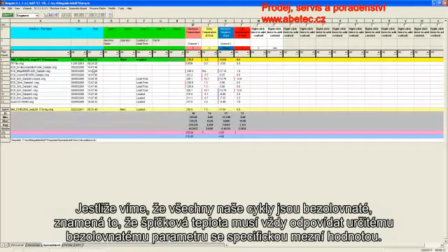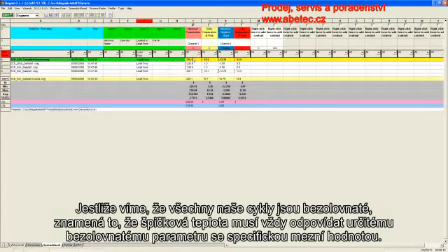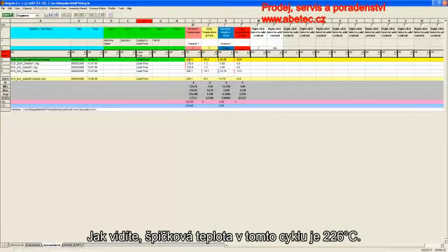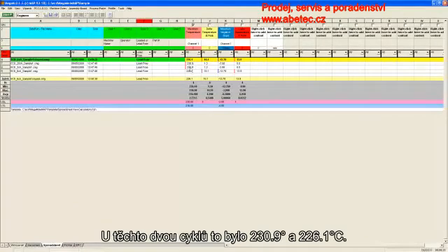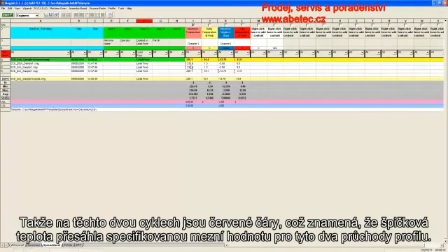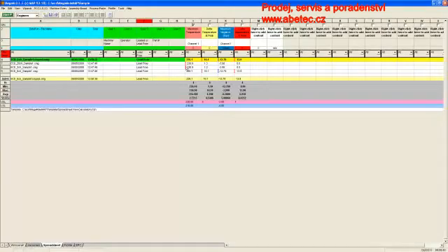If we know that all of our runs are lead-free, that means the peak temperature should always be within a certain lead-free parameter, which you can put a spec limit around. You can see that the peak temperature is 226 on this run. It was 230.9 on these 2 runs and 226.1. So there's red bars on these 2 runs, meaning that the peak temperature exceeded our spec limit for these 2 profile runs.